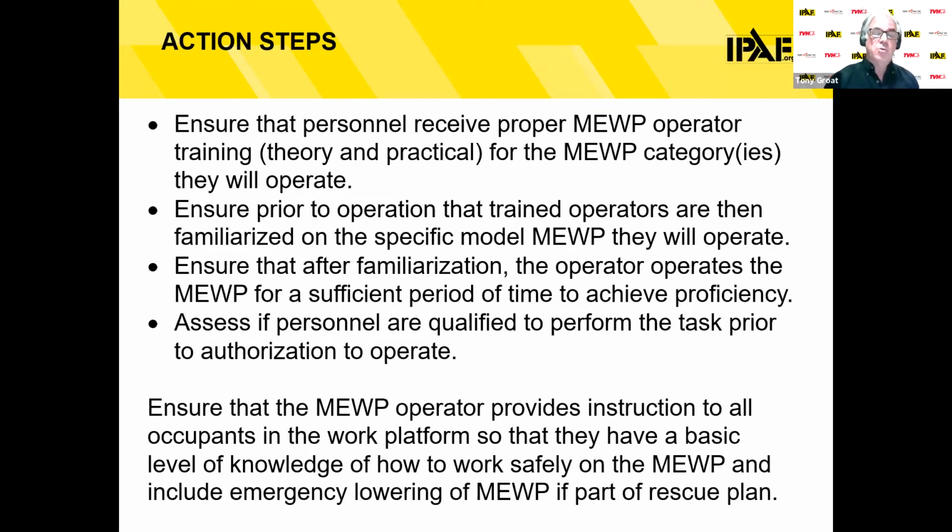Again, you need to ensure that the MEWP operator provides instructions to occupants in the work platform as well, so they have the basic knowledge of how to work safely out of that MEWP platform. And that could potentially include how to use the emergency lowering of the MEWP as part of your rescue plan.